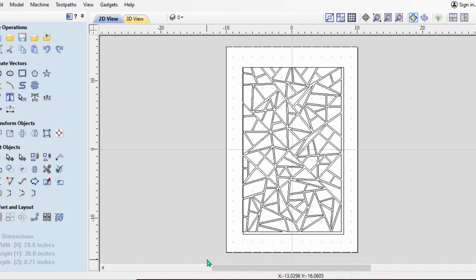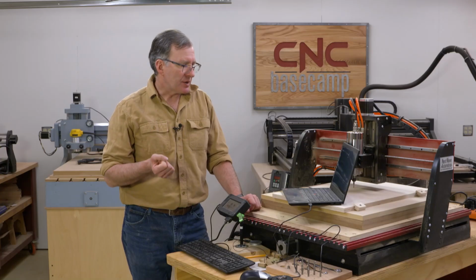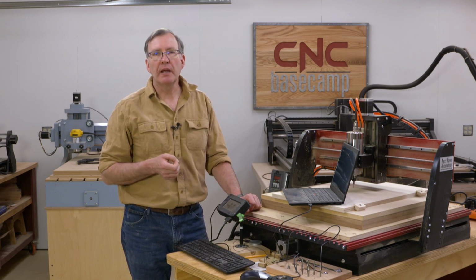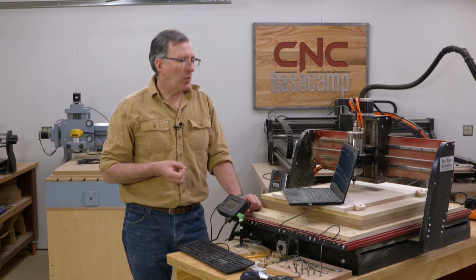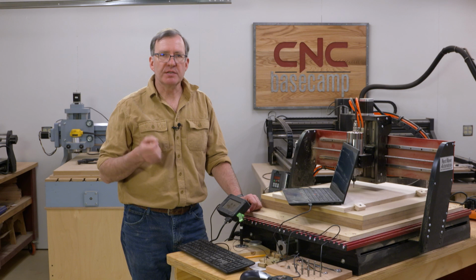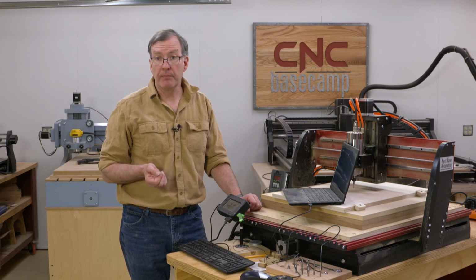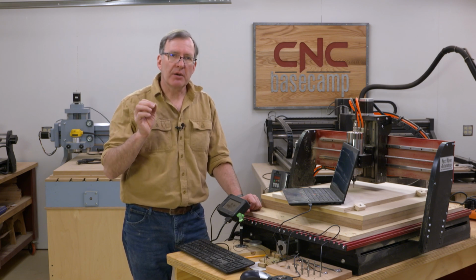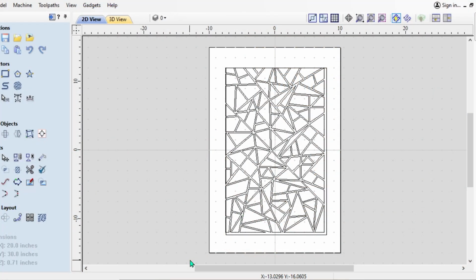As you can see here on the screen, this is the DXF file for that part that I had in Autodesk Inventor. And so what I'm going to do then is create a pocket cut of all those shapes. I'm going to use a straight bit because that gives a nice clean cut in plywood, and I'm cutting 1/8 of an inch deep. I'm choosing 1/8 simply because that's the minimum thickness that I can safely plane wood with my planer. So let's go ahead and get the CNC all set up, and let's start creating the pockets for our geometric design for our stained glass door.